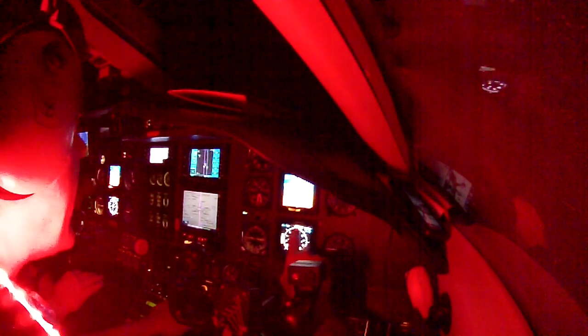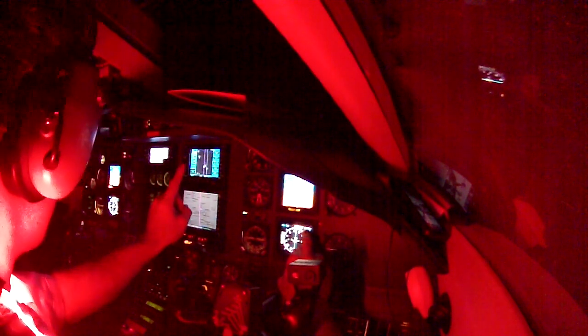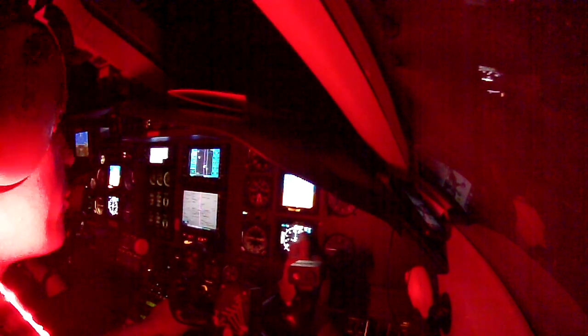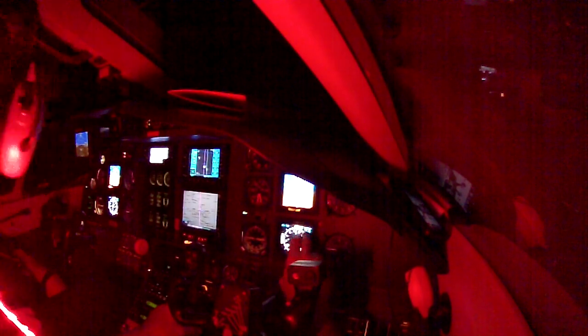To the right, we have heading 1, which is the HSI getting information from AHRS 1, the heading reference. AHRS is the attitude and heading reference system. We have 423 nautical miles to our next checkpoint of RBV, not the destination. It's 422 on the 530. Below that, 297 knots ground speed. Below that, the time, 1:25, one hour and 25 minutes.